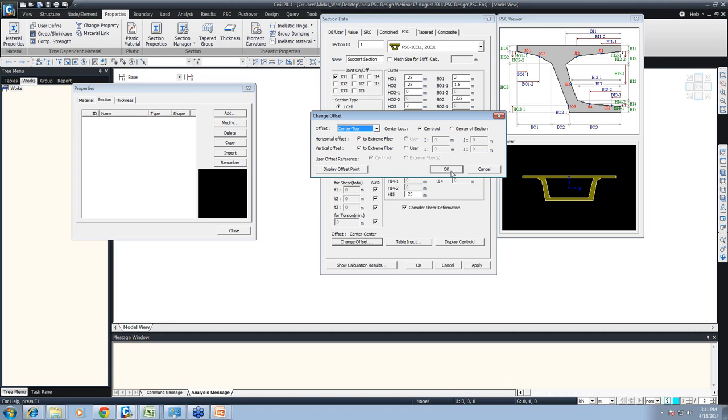Why did we change the offset to center to center top? Because more or less we are tapering somewhat like this. I will just explain to you that my actual element is a line element, simple line element. Okay. So suppose if we want a tapering of a rectangle, and we want to taper it something like this. So my top surface is uniform in that case, right? But if we give center, what it will do, it will taper from center to center. So it will taper in all directions. It won't be uniform properly.